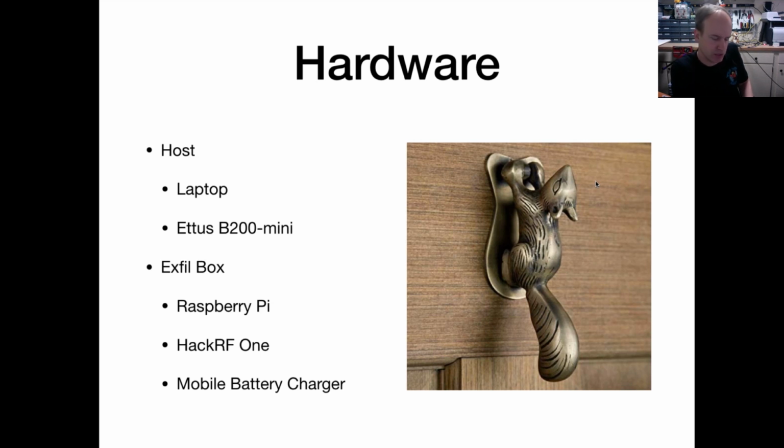But it also doesn't require USB 3, and you can run the Ettus board on USB 2, but you run into some issues, and the same amount of data actually takes more USB bandwidth. I can get into that if anyone's interested, but the HackRF One is a better match for the current Raspberry Pi setup with its USB 2 ports.